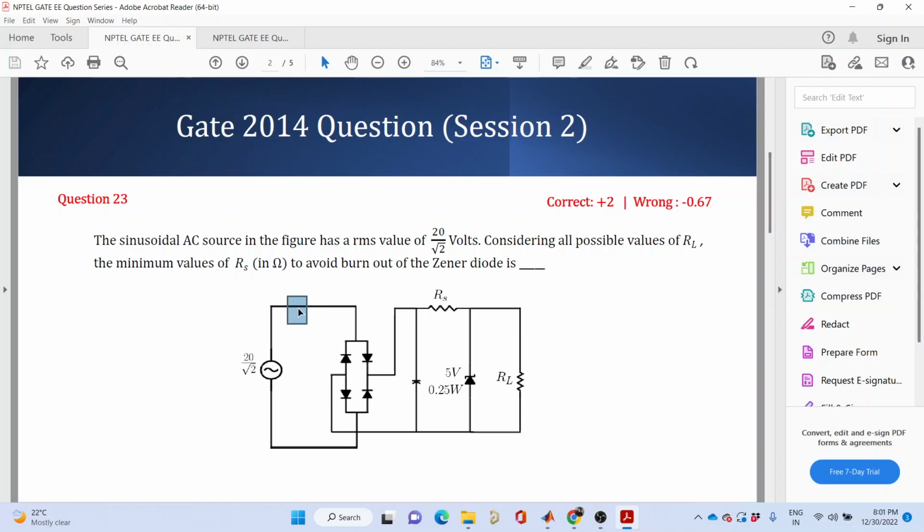If you turn this on, during starting the capacitor is totally discharged. The voltage across the capacitor is zero. Correct? Yes, sir. So now if you turn on the switch, what you are actually doing is shorting these two points. Correct? Yes, sir. So what would happen is it will burn away.